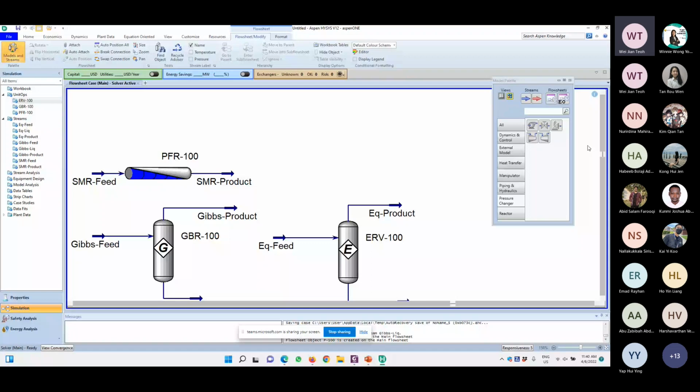The issue with doing that is you sacrifice the bottom component purity, because if you have a higher reflux ratio and a higher boil-up ratio at the reboiler, you would have a higher bottom component purity. So if you get a very high reboiler duty, then you might need to think of reducing the boil-up ratio and the vapor flow to see whether you can still achieve what you want with these lower parameters. If not, then it means sacrificing the bottom purity. Just drop the purity and you see your reboiler duty drop a lot. So that would be my answer to your question. I hope that helps.